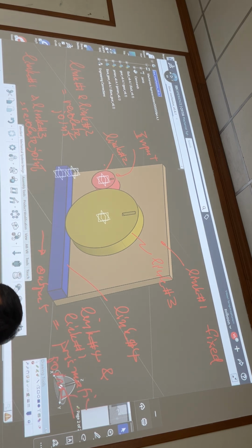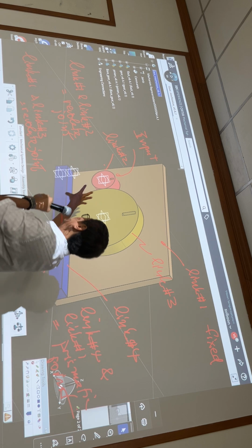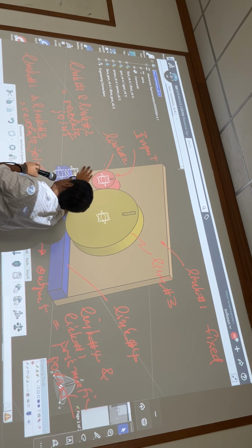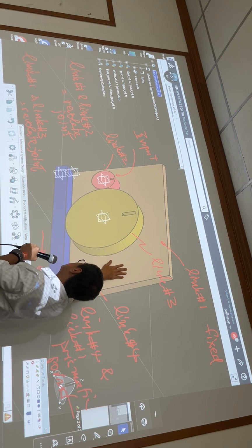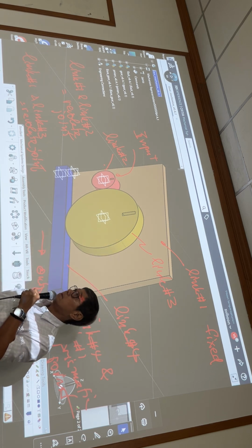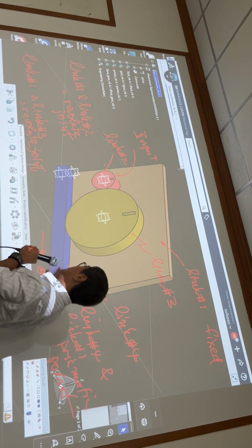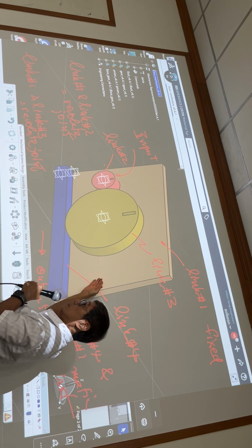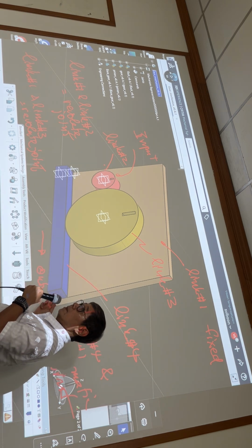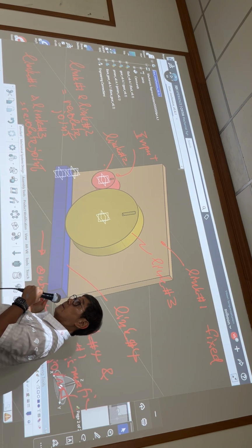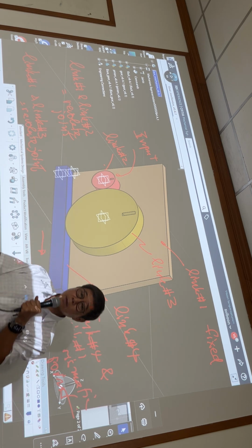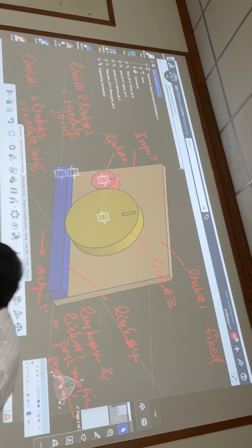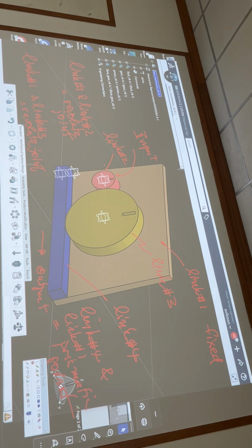Right? This one and this one should be revolute joint. This one and this one should be revolute joint as well. This one and this one, slide this one, should be a prismatic joint. Right? Prismatic joint slides this. If you assign only this, it's not enough anyway.